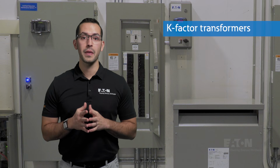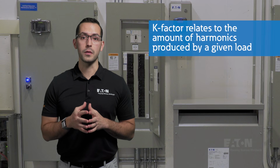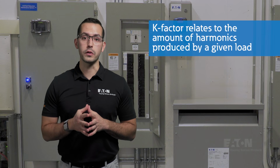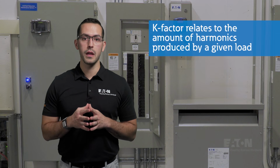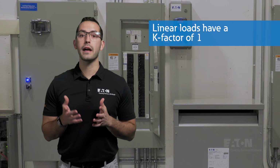K-factor transformers. K-factor is a common industry term that relates to the amount of harmonics produced by a given load. The larger the K-factor, the more harmonics are present. Linear loads, for example, have a K-factor of 1.